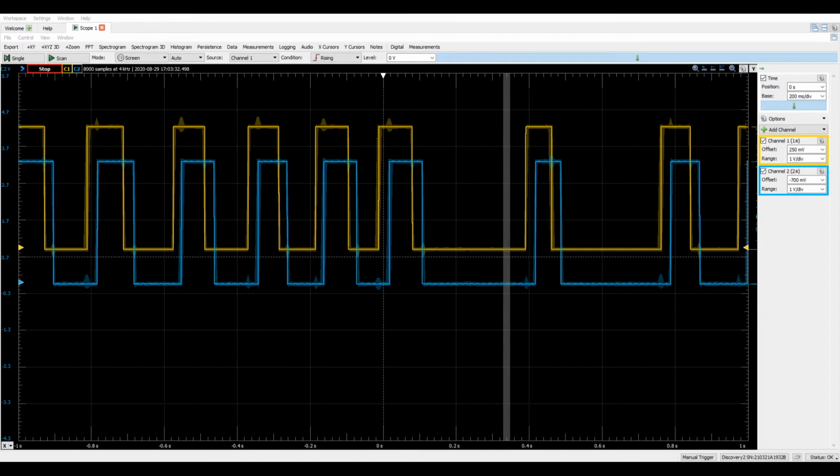What you see here, the yellow is my input, which is my switch, and the blue is my output, which is the debounced version. You still can't see it clearly, and the reason probably is because I'm taking that output to the jumper. It's not really the output you get from the switch directly. It's the output that passed through the FPGA, and then the FPGA routed it out. So you're not going to see the debounce very clearly. Or it could also be that my scope is not very clear because it's a USB version.